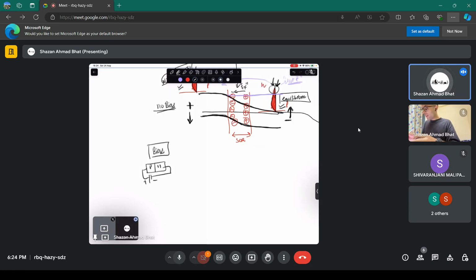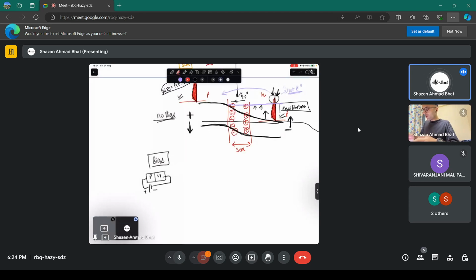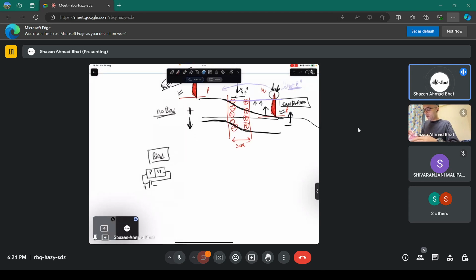The electrons already had that particular distribution that it can go across the barrier, over the barrier. But it didn't because there was a barrier up to this purple level. Now you are raising this particular barrier. Now more number of electrons are going to come out from the Fermi distribution.